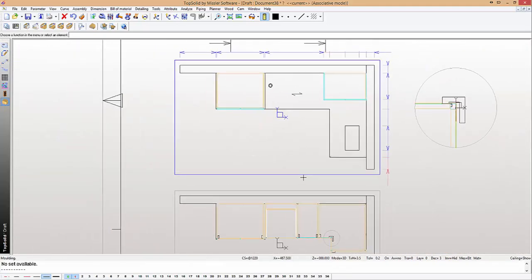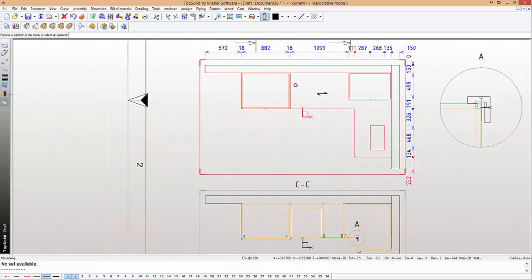But also, what I can do is go to this view and click on my molding dimension and just click on that edge there. And it actually brings out that information, so you don't have to be typing it up. Okay, making life easier once again, reducing mistakes, giving more information down to the floor and to the architect, bettering communication.